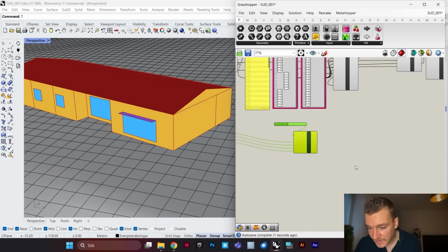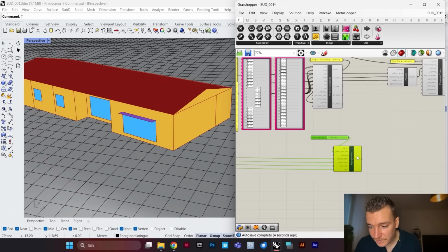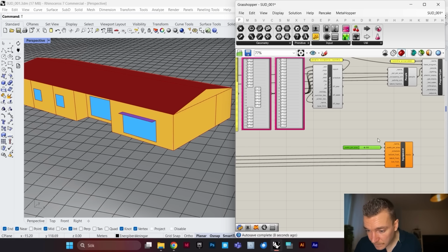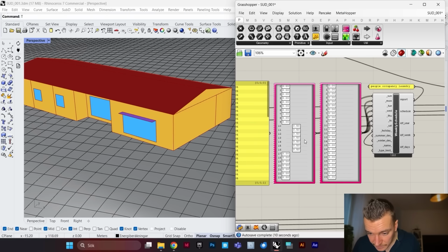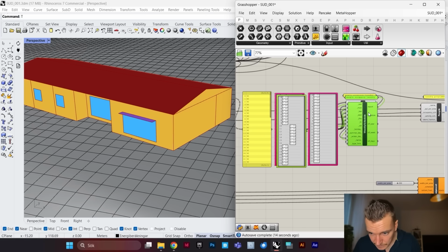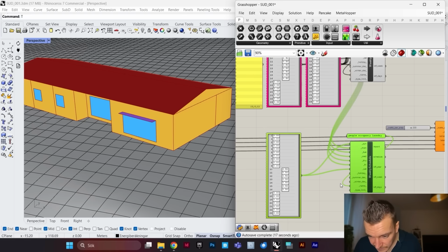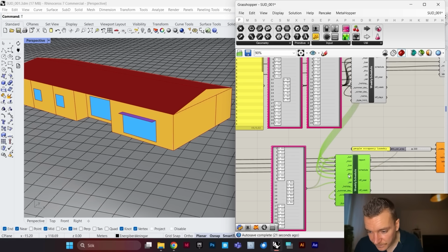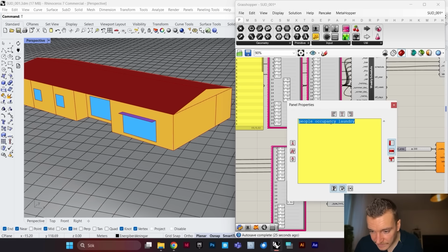But we also want to create a new schedule for these loads. So we are going to copy these 3. In the weekends, in the weekdays, we're going to use this 0, 0, 0, 0 schedule and name this electric equipment laundry.